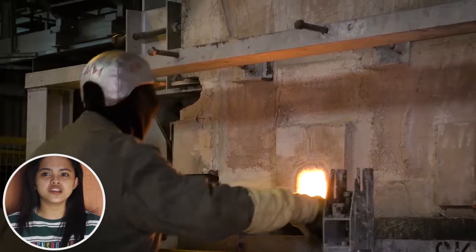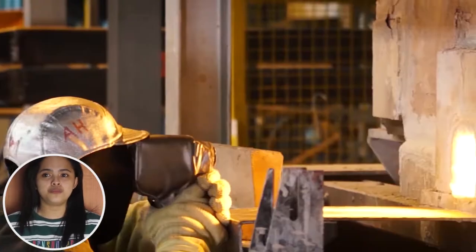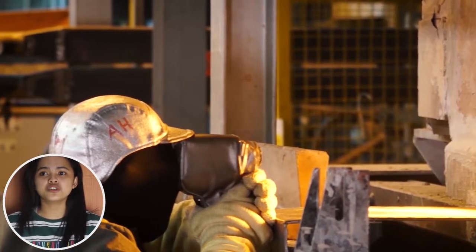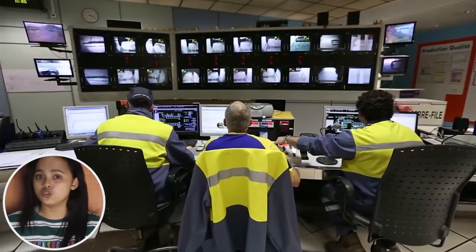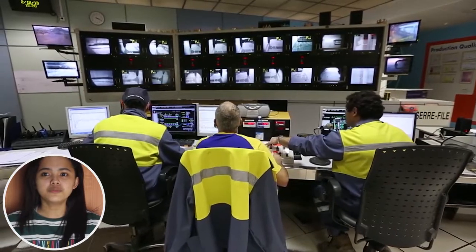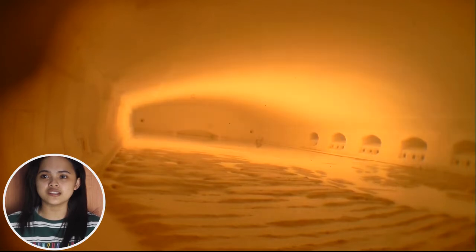The process within the furnace is continually monitored by technicians who take measurements inside and from the screens in the control room. The flames develop above the furnace. Every 20 minutes, the direction is reversed to optimize the thermal balance in the furnace and the efficiency of the flue gases heat recovery chambers.